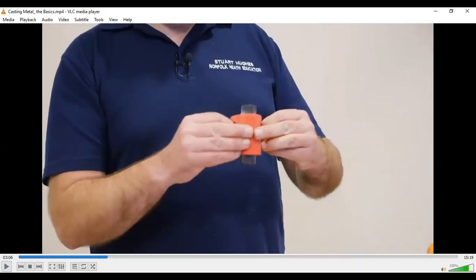Right, as I said, we could just make a solid casting and then drill a hole through machining. We have CNCs, we have lathes, but that is one way to do it. As I said, to produce a component, there are a lot of ways that you can use. But to look at the optimal processes, if we can have this core, what he's showing, then we can produce an internal feature in just one process instead of having two processes, instead of having to send it to CNC or somewhere else. So to reduce the processes, they're using a core so that the internal feature can also be generated.